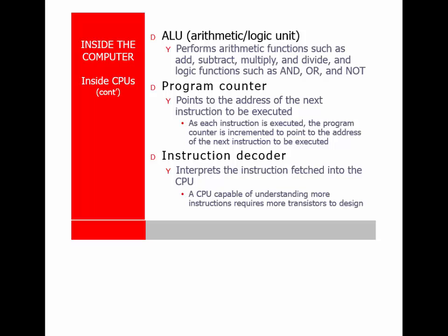Obviously, a microcontroller system is much smaller because you've eliminated the RAM chips, the ROM chips, the I/O controllers, and probably the A to Ds and D to As. In most cases you eliminate the clock module and all that stuff. It's all right inside the same chip. The disadvantage is microcontrollers tend to be relatively small.